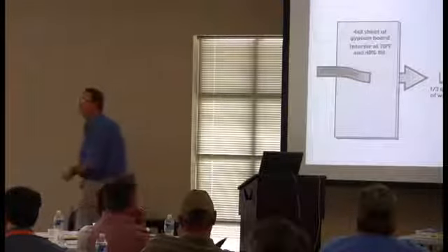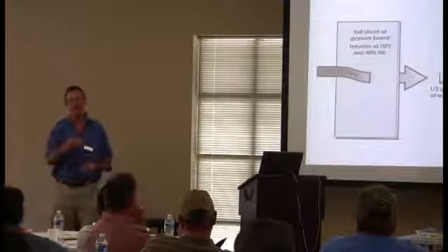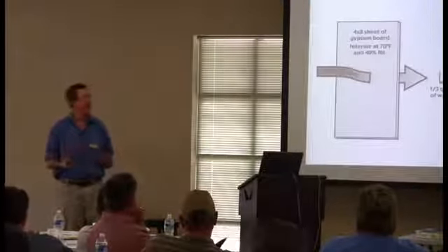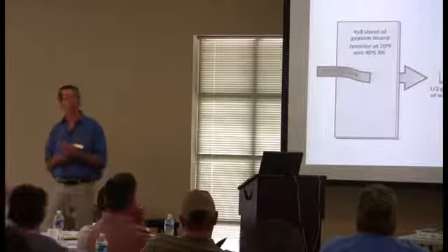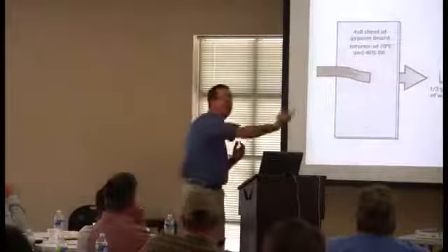So a vapor retarder really can get you into trouble in our climate because it actually can trap moisture when you don't want it to. And the reality of it is we are not in a one-way climate. We're in a two-directional climate where water vapor is going one way and then coming this way.